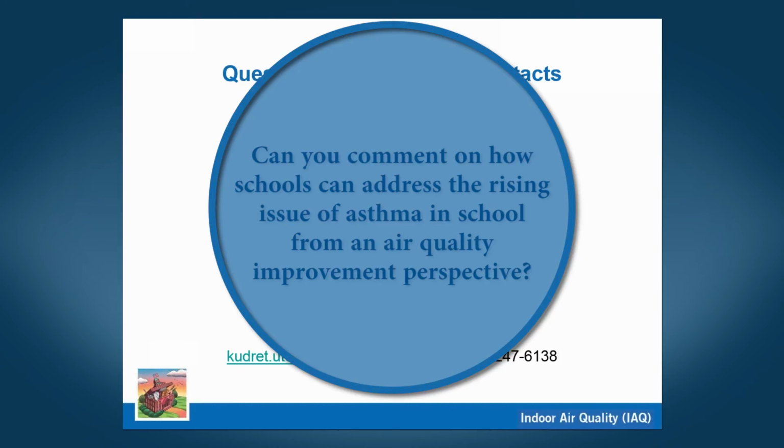And David, jumping on your comment, in some systems, it's potentially feasible to redesign the filter rack so that it can hold a 4-inch deep pleated filter as opposed to a 1 or 2-inch deep pleated filter, which then gives you lots of flexibility for high efficiency air cleaning. But the key words there are some and redesign. It's very easy to do in most homes. It's harder to do in schools.